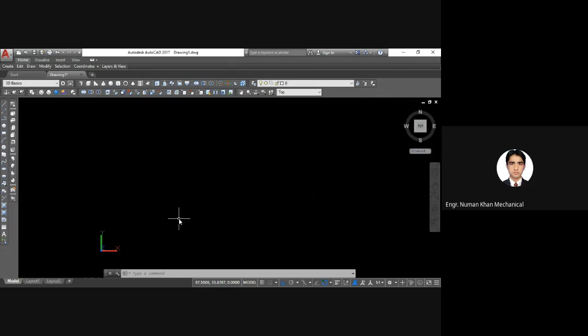This can be done using the loft command. Any other command cannot do this, so we are bound to use the loft command for such types of objects. For doing this, we need the objects to be drawn at different elevations from each other. If you remember, while discussing the rectangle command, we talked about elevation, in which we drew three different rectangles at particular heights from each other. So that can be used over here.